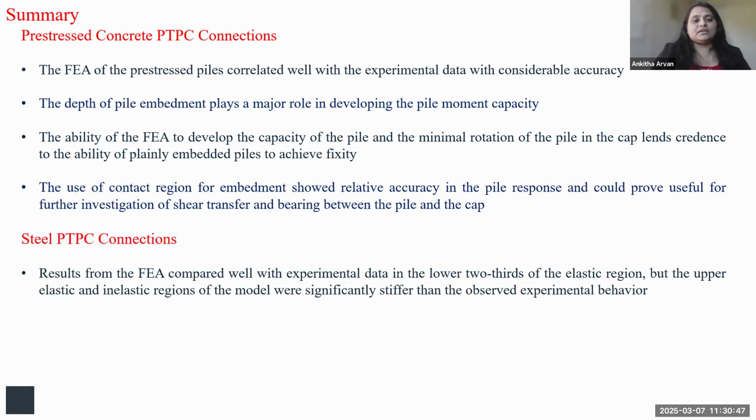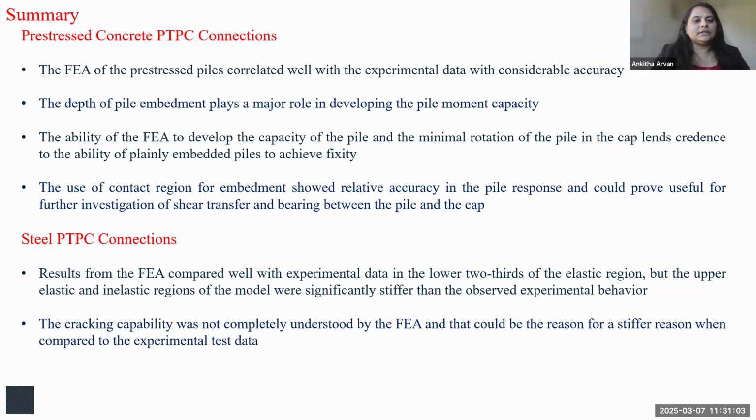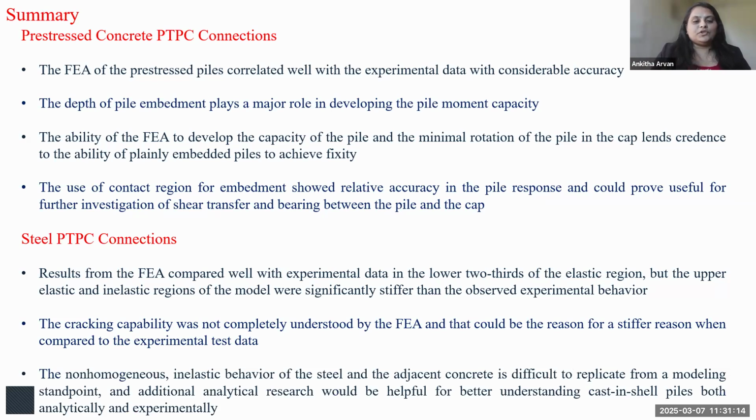For steel PTPC connections, the FEA compared well with experimental data, as we saw, in the lower two-thirds of the elastic region, but the upper elastic and inelastic regions were significantly stiffer. Refinement of the numerical models would help understand it better. The cracking capability was not completely captured by the FEA in the case of steel PTPC connections, and that could also be a reason for the stiffer response. The non-homogeneous inelastic behavior of the steel and adjacent concrete is usually difficult to replicate from a modeling standpoint, so additional analytical analysis would be helpful in this case.